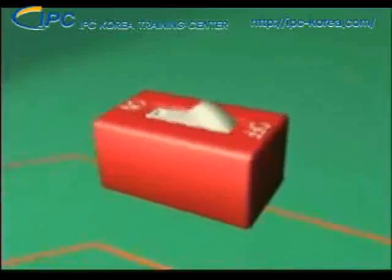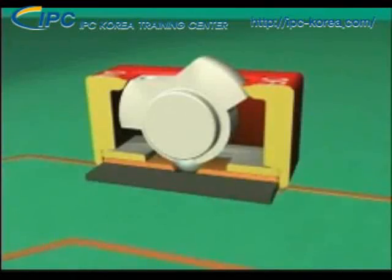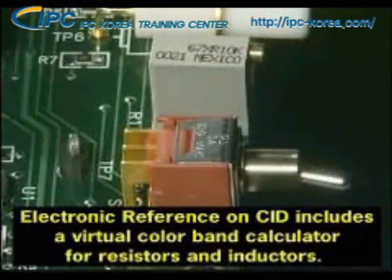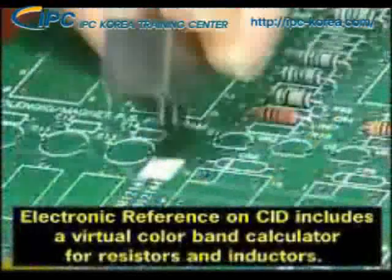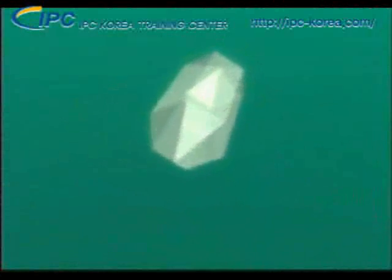Now we'll talk about switches and relays. Switches and relays open and close circuits. Relays are electrically operated switches. The reference designator for a switch is the letter S or SW. A relay is usually designated by the letter K. These components are measured in amps and volts and utilize a dot or notch for orientation.